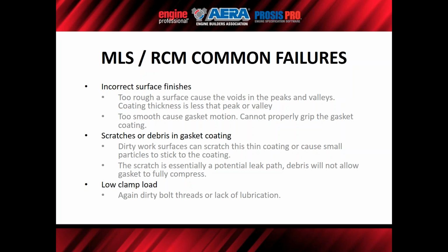So if you make it really smooth, then the gasket can't be gripped by the little peaks and valleys enough, and then you have gasket motion, and you don't want that. You want an actual nice tight grip. Let the peaks and valleys grab the gasket and hold it in place. Another common issue that we see is scratches or debris in the gasket coating.